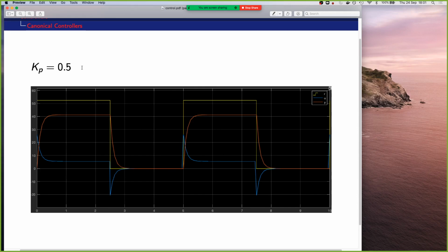And that's with a gain of 0.5 there. This is the type of response that we get. So this behavior here may not be super ideal. Why is this happening? We've told our reference is a bit over 50 and we're only hitting a little bit over 40. That's not ideal. What happens if we change the gain of our feedback controller?